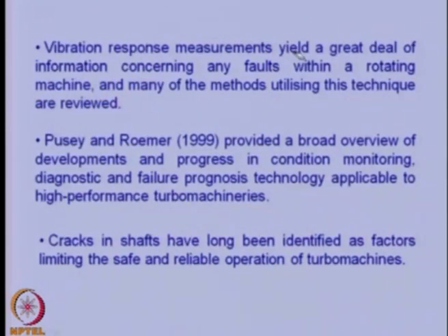Vibration response measurements yield a great deal of information concerning any fault within a rotating machine, and many of the methods that utilize this technique are reviewed in this particular paper. Some other reviews provided a broad overview of development and progress in condition monitoring, diagnostics and failure prognosis techniques applicable to high performance turbomachinery.